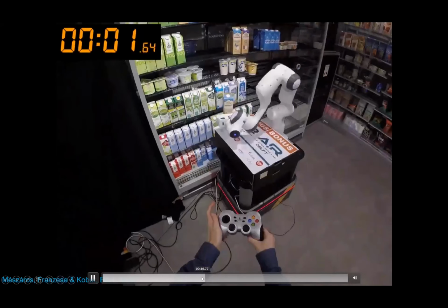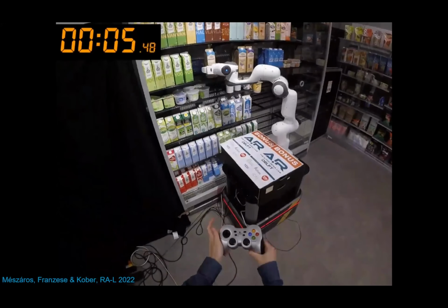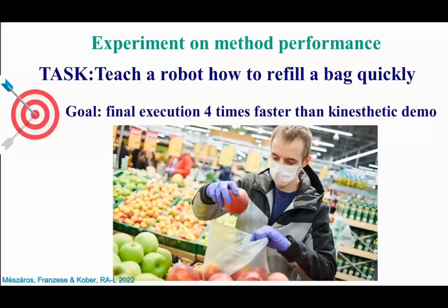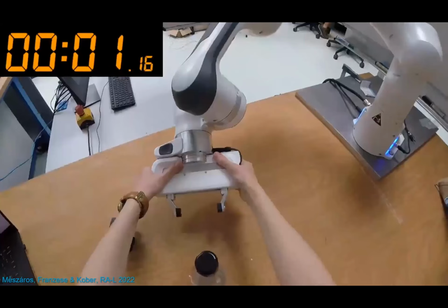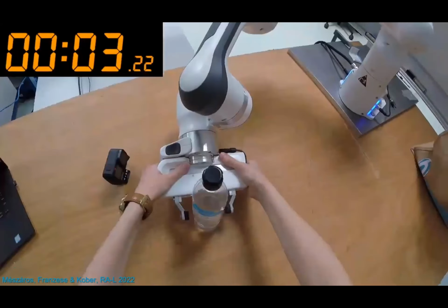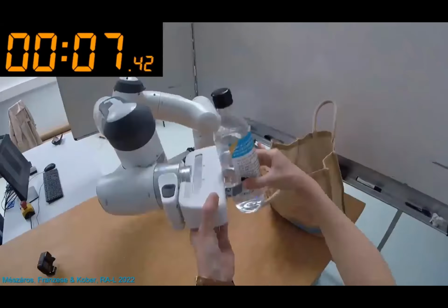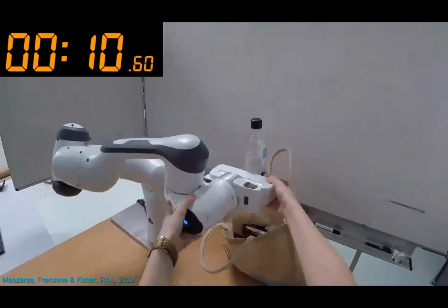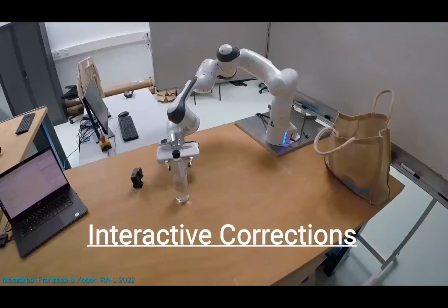So one interesting thing here, I'm not sure how many of you are working with pandas, is that the gripper is a bit iffy in terms of timing. It's totally random within a fraction of a second when it closes. So also here we actually needed to make use of the interaction of having a nice movement of pushing the bottle, so we actually get robust to the exact moment of closing.